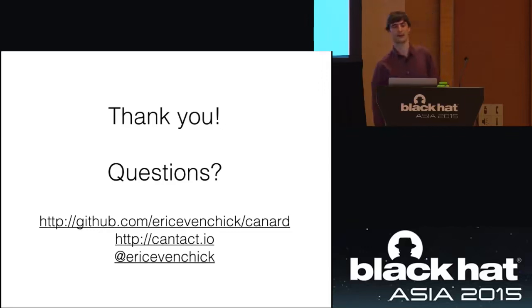So it sort of depends what level you want to do it at. You can fuzz a raw CAN bus, which I didn't talk about too much, but actually someone I was talking to today was doing that with planes, which sounds terrifying. But essentially, you can send arbitrary data in messages and see what the responses were.